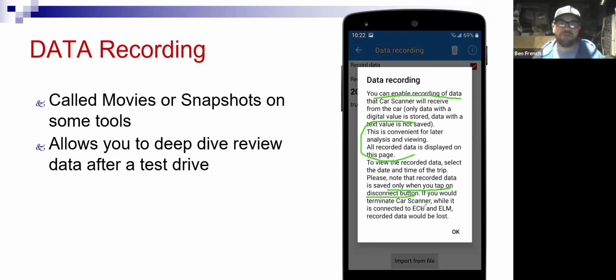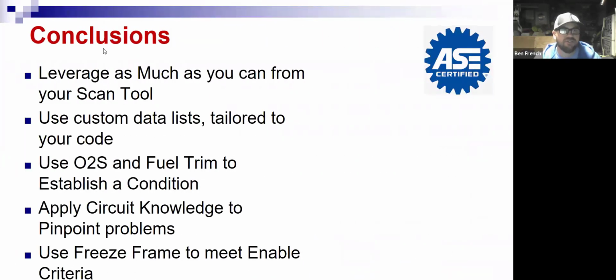It's always recording it in a data buffer, but it won't actually save it unless you go in here and hit disconnect. And then once you do that, you'll see a file saved with a time and date stamp of when your recording is for you to review. Okay, so when you get a dialog box like this that comes up, always read what that says. So I recommend to always do data recording so that you can focus on driving and you don't get in a wreck with your customer's car as you're trying to diagnose it.